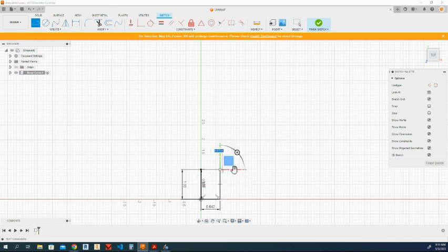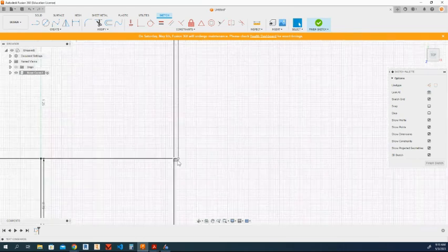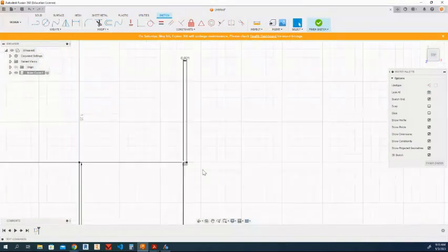Now I need to get my nose cone out. From this point here, I need to come out. This thing is going to be my nose diameter, which is 1.325 minus my shoulder diameter, which was 1.283. I need all of that. So I'm going to put this in parentheses, divided by 2. What that's created is this little step out for me, which is what I needed.